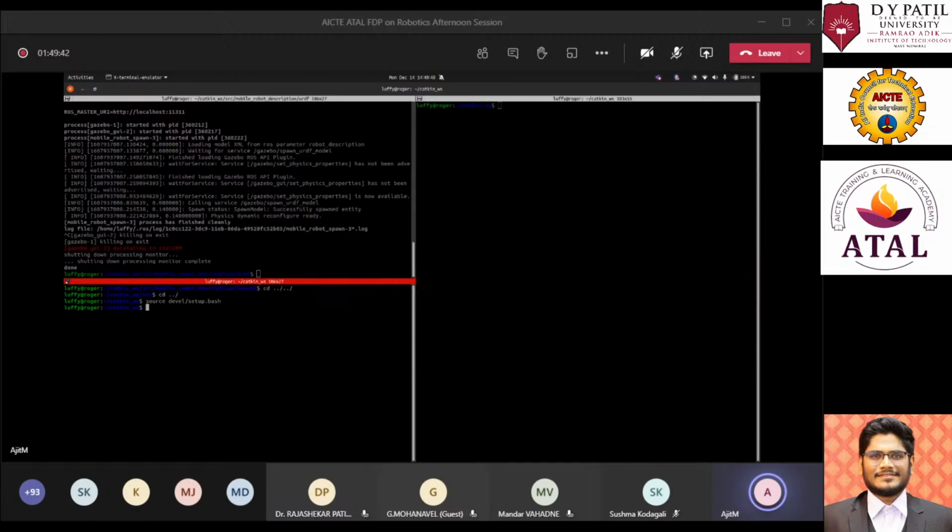And one thing which we need to mention while using xacro is we have to define the namespace. So this is the XML namespace for xacro, and this is the link to that namespace. Now let's see whether it compiles.